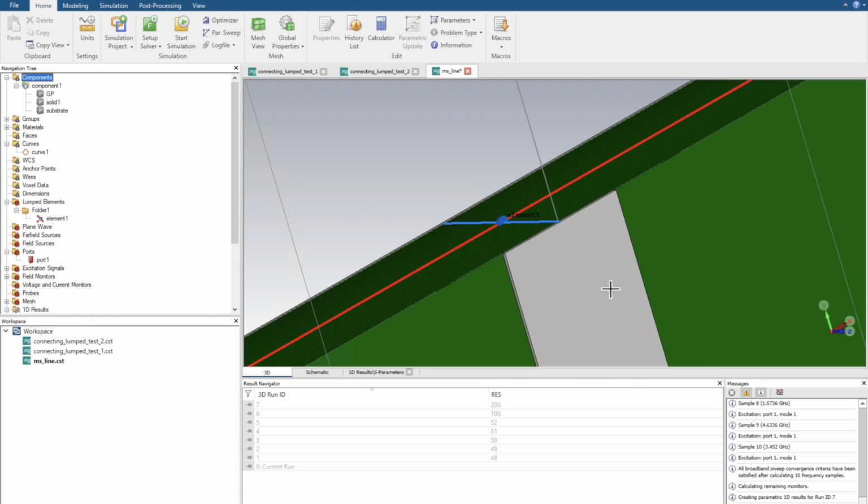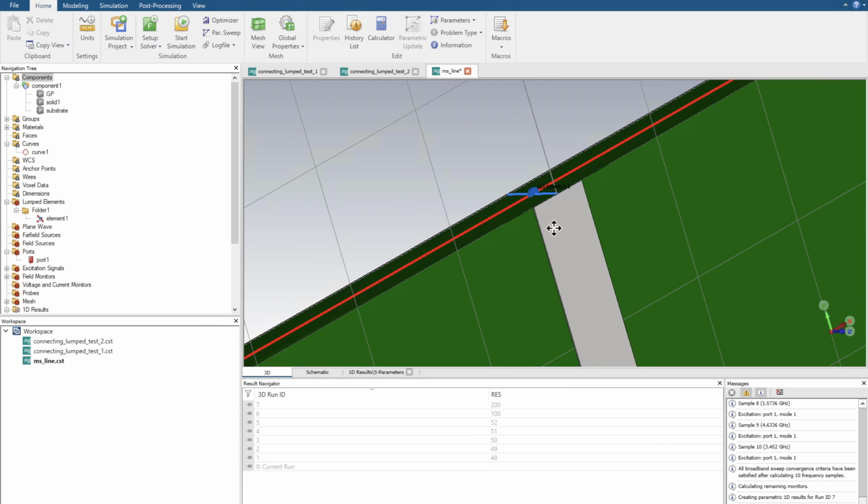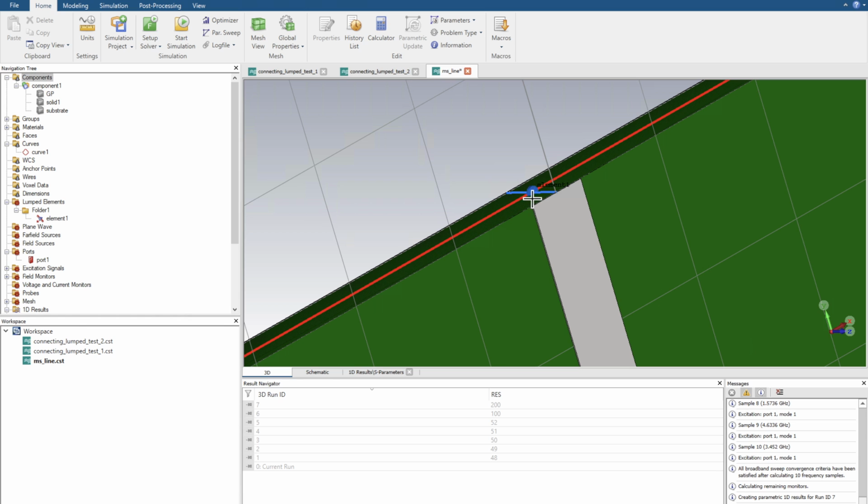Okay, the simulation is done now. I encountered one error: when you create a lumped element port for the first time, that is when you need to put in your variable name. I had set it to an integer value of 50 and then applied the variable name after creation by editing the history tree, and it seemed not to have worked, so I resimulated and replaced the lumped element and simulated for the exact same conditions as before.